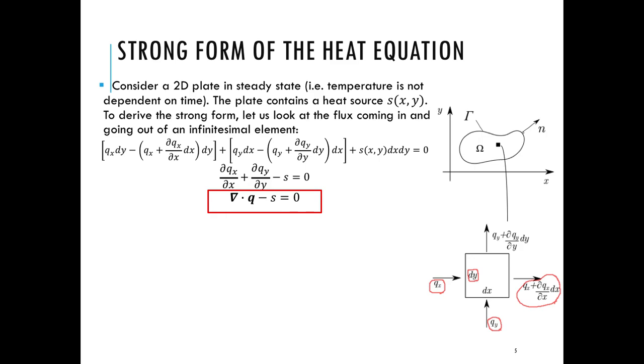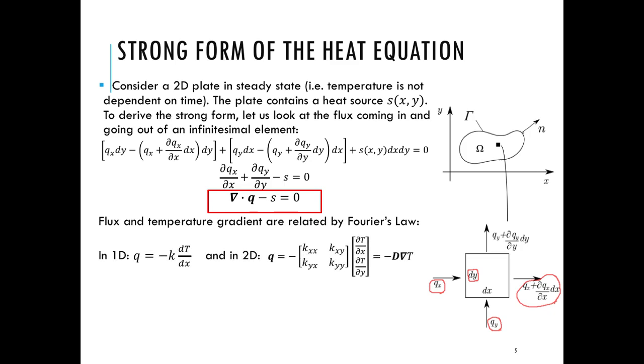So we can also have a constitutive material law, which tells us how the heat flux inside a body is represented for a given material. In this case, the material law is given to us by Fourier's law, which basically tells us how the heat flux in a body, q, is related to the temperature gradient within the body.